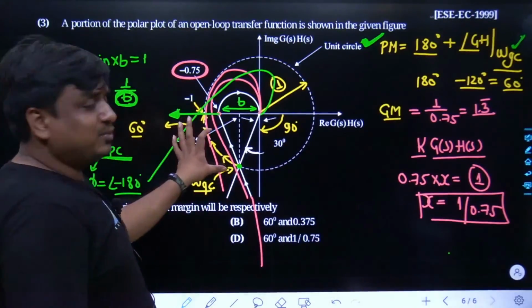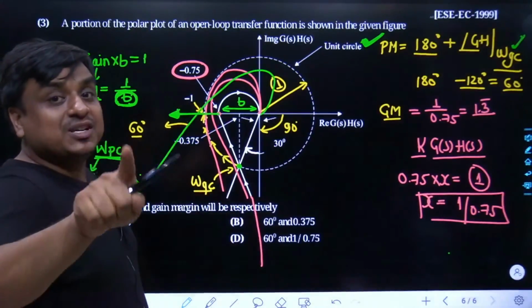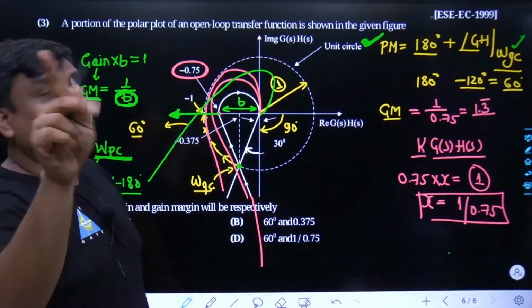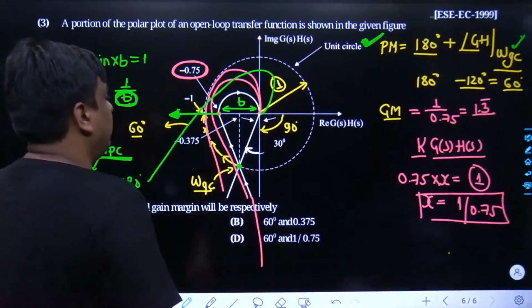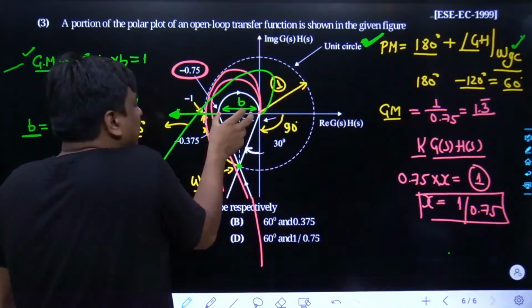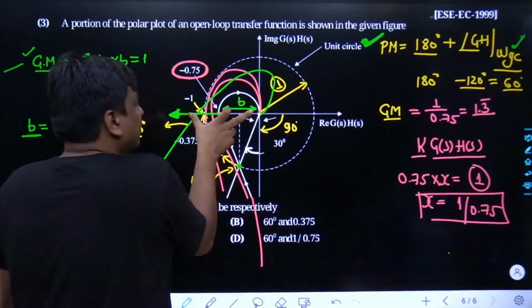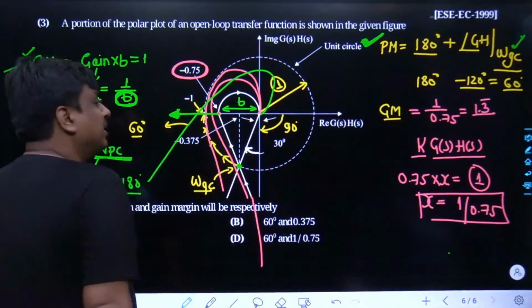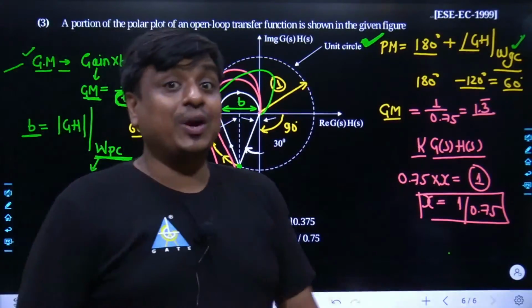So how much margin is being left out? It's nothing but the margin which has been left out in terms of phase lag, the phase margin. Similarly, in future, when the gain keeps being pumped up, what would happen? This point would keep shifting from its place towards the left hand side, and probably the minus 1 plus j0 is going to go into danger.